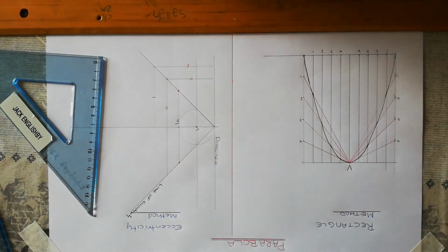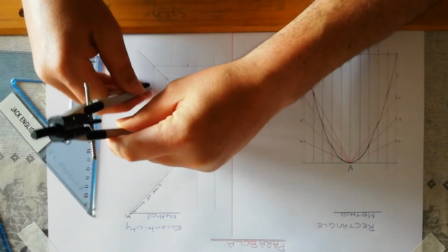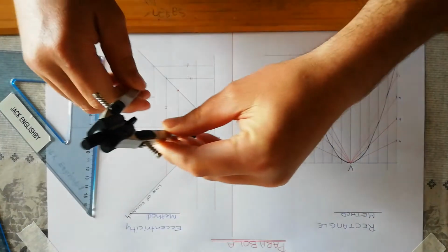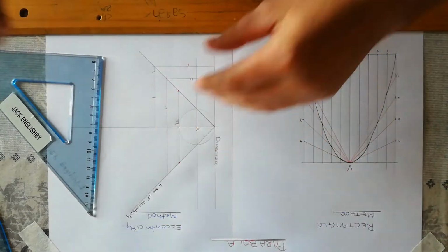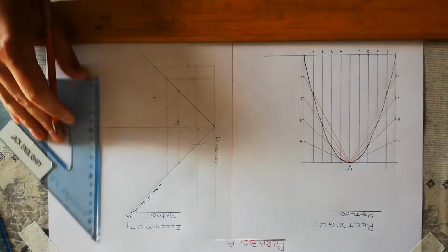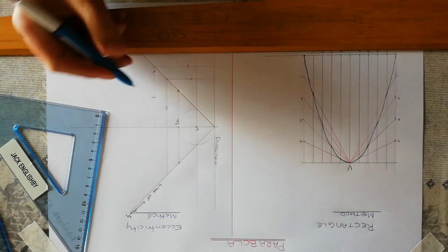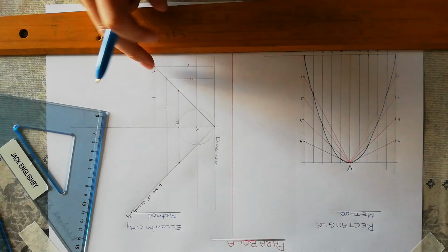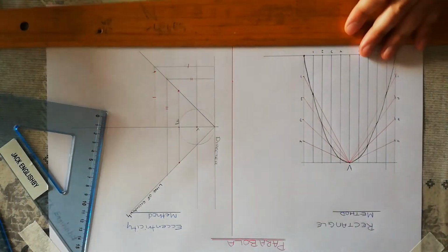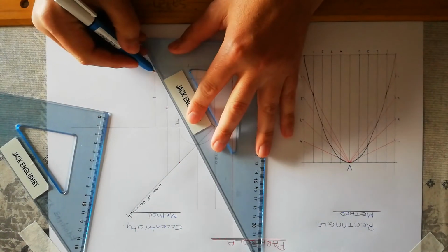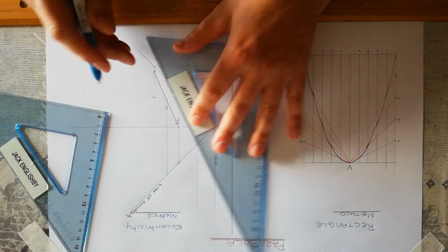So what we do is we take the height of each point to our line of eccentricity, and we swing it from the focus. And we now know that that is a point on the curve. Why? Because that distance has remained constant and that distance has remained the same too. So we now have a line from the focus to the point in the curve.